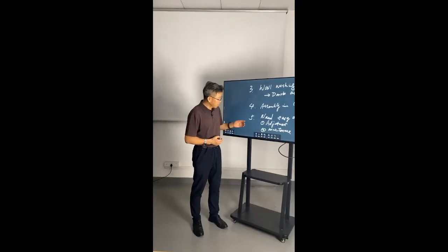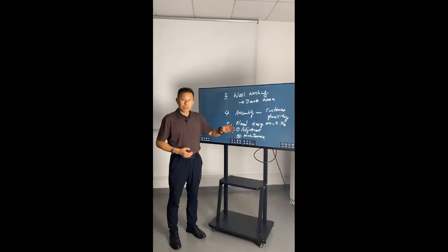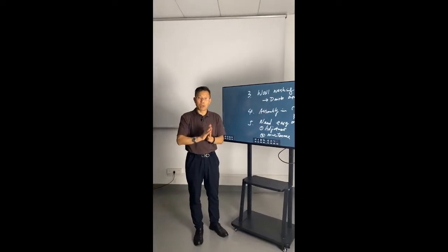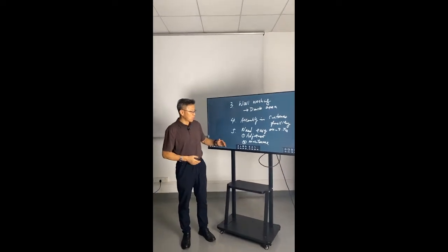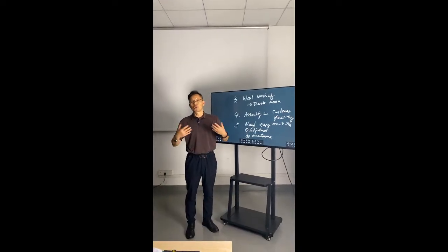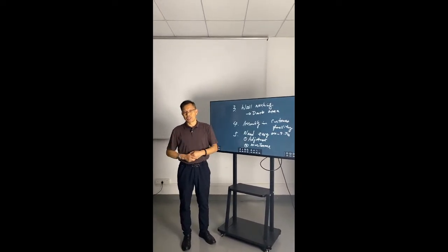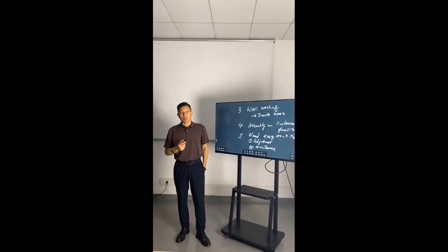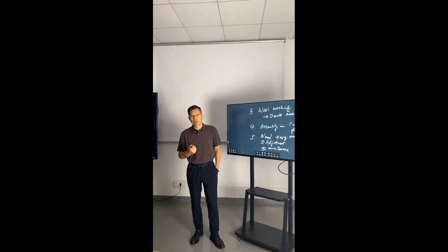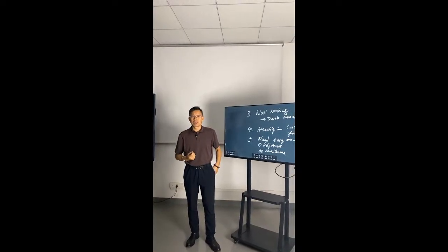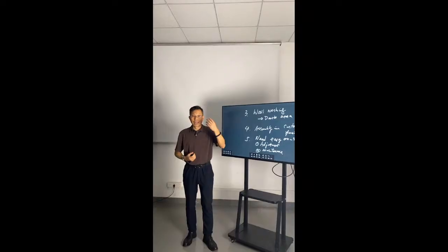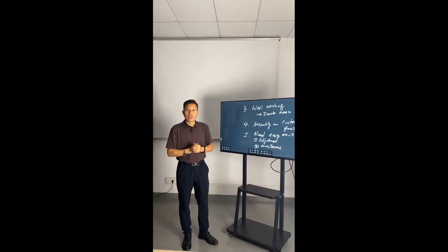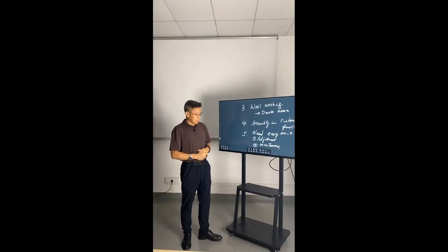And number 5 is the easy adjustment on site of the beam angle, beam direction, and also the easy maintenance if something goes wrong, whether it is the driver or the LED engine, because through the cutout and the mounting trim, we can take off the driver and the fixture itself.